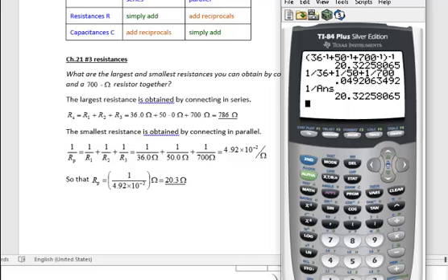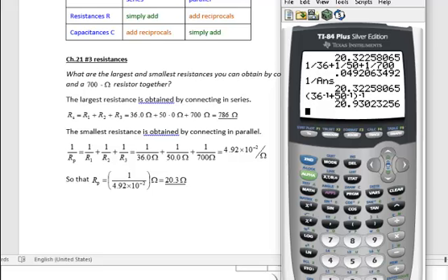By the way, I mentioned something about that. Well, does the 700 really matter in a parallel circuit? So let me go back to that one. There we go. So notice that the answer would be 20.3, but what if I actually don't have anything there? Ooh, that's not going to work. I didn't mean to do that. It would have to be a really large value. So if I just leave it out, notice I get 20.9 ohms.